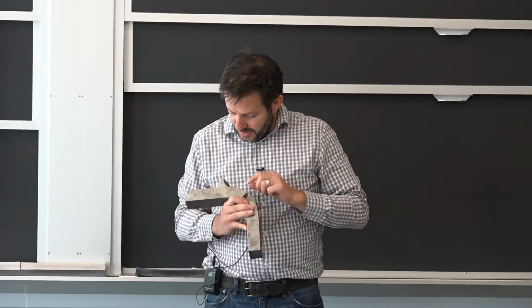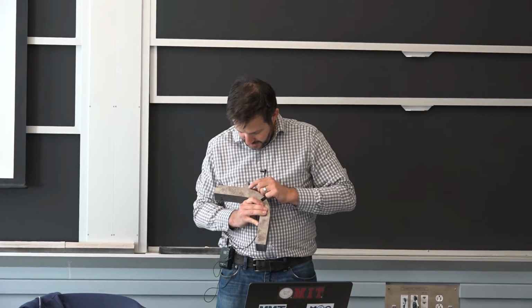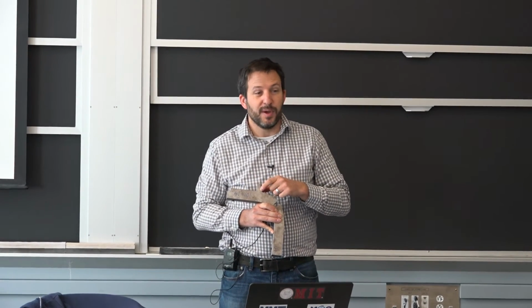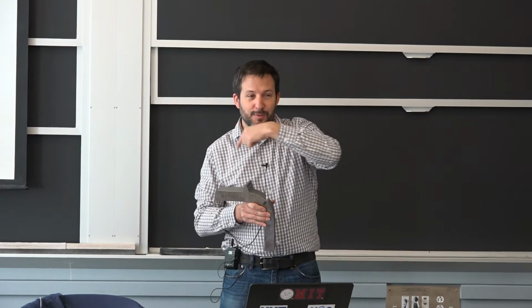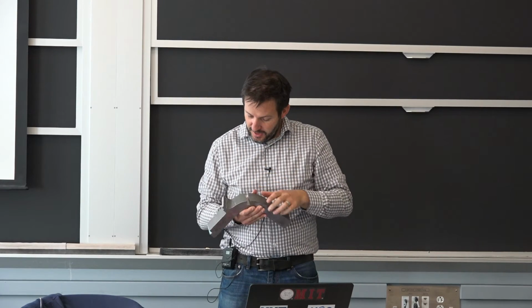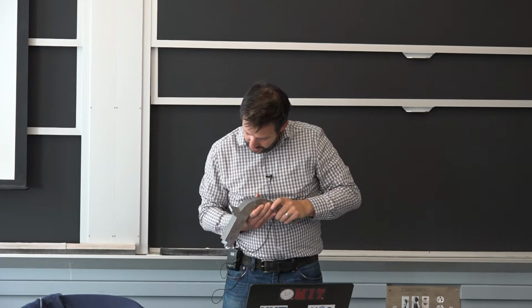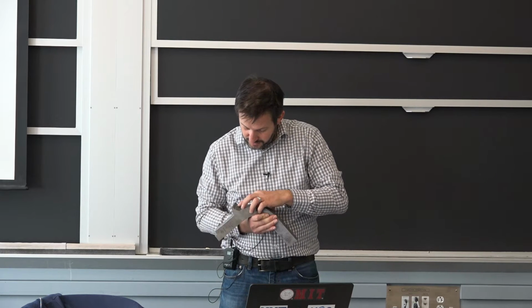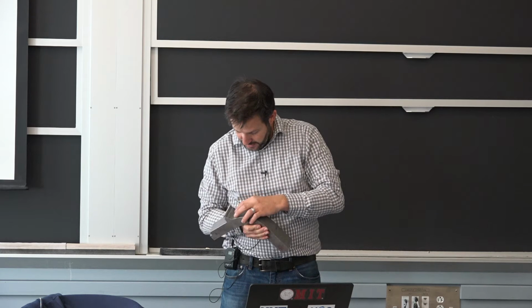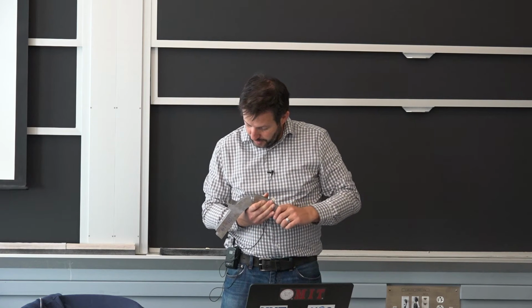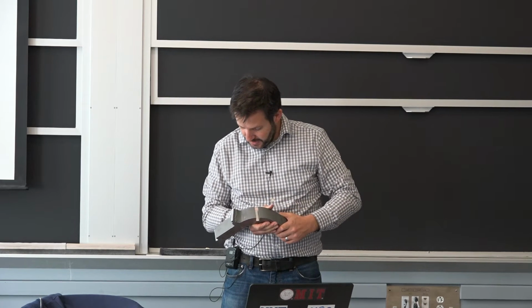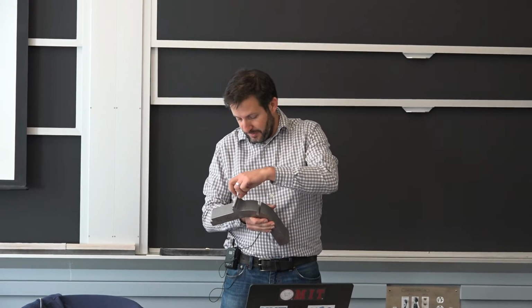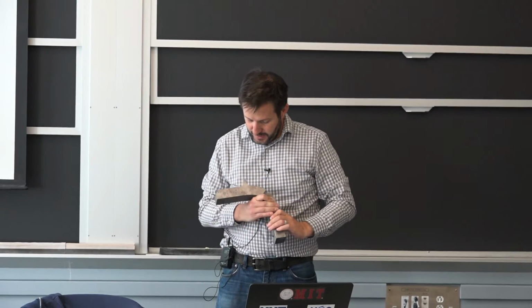Another feature is you have at least 5 welding passes. So they went once, went again, went again, went again, and on the top surface, you only see 2 of them, and one is very wide. It was a little bit wider than what you would normally want to do for this thickness.